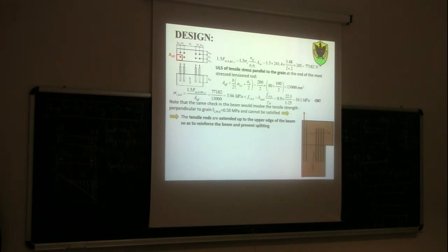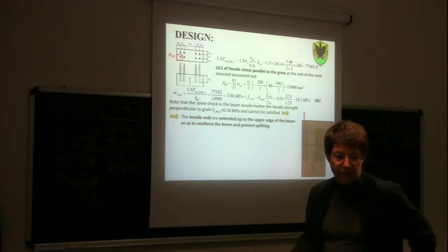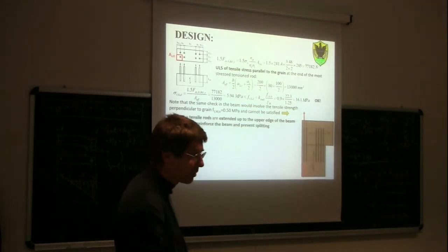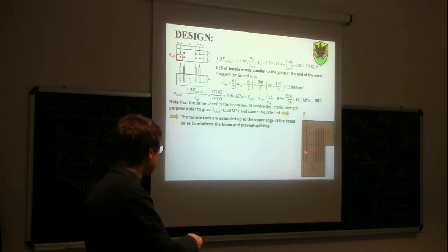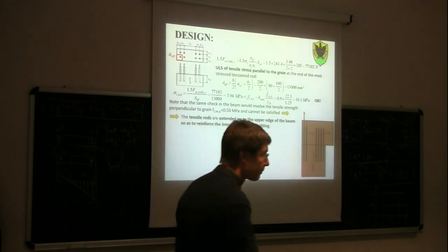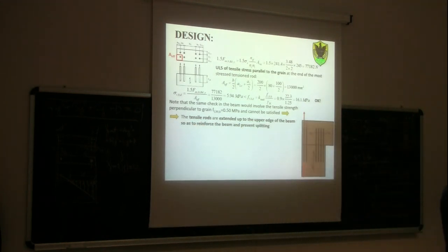Okay? Of course, doing this is quite demanding in our case because our beam is 1.6 meters deep, if you remember. So it means that you have to have a rod which is 1.6 plus another 1 meter, so 2.6 meters. As you can imagine, to glue a rod which is 2.6 meters into holes which are just 2 or 3 millimeters wider and which are 3 meters long, it's very difficult, very complex. That's why I said that this is a more theoretical exercise, because you can design something like this, but constructing this joint would need a lot of help for whoever has to do it.